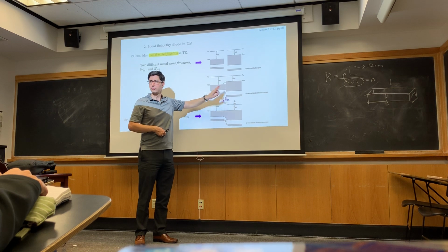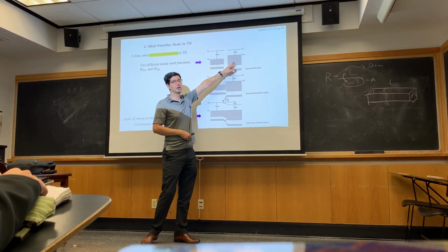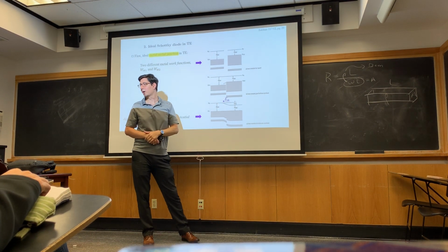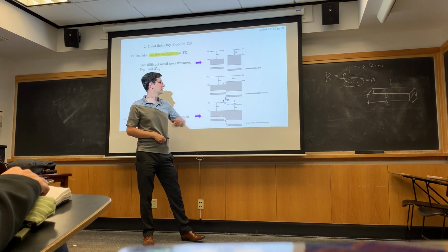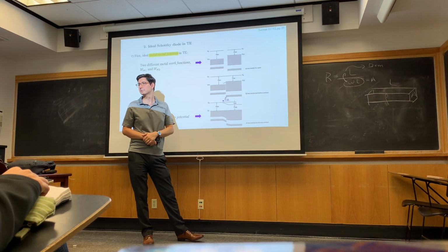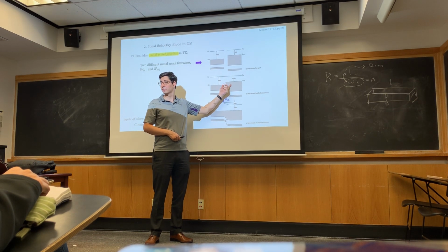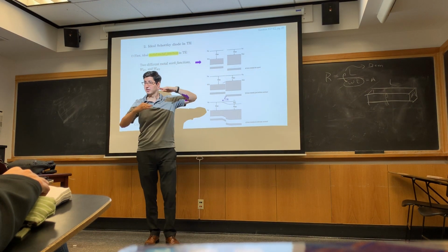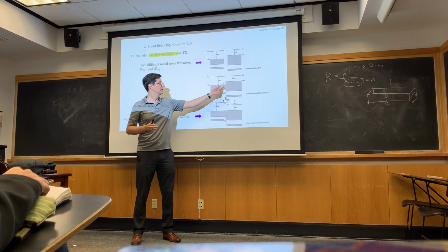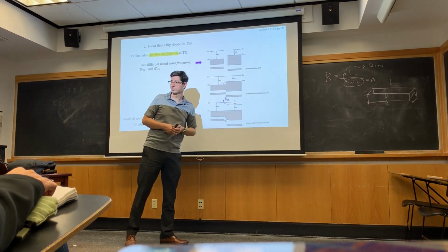Now, what happens when electrons leave this metal? Did this metal come in charged? So when negatively charged particles come off of it, what's going to happen here? It's going to leave behind a positive charge. That's going to set up an electric field. That's going to change the effective potential across the junction. There's going to be band bending, and that electric field is ultimately going to stop diffusion at some point. All of the electrons don't flow all the way.